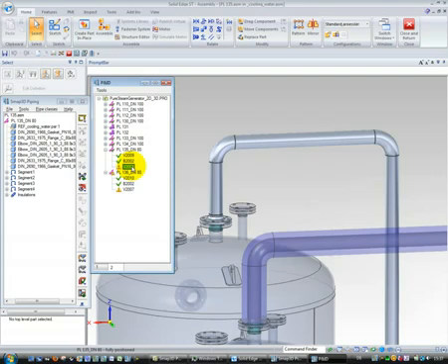And normally a valve is a kind of inner equipment, that means it belongs to a pipeline. So if it belongs to a pipeline and if this valve does also belong to the pipe spec which we worked with at the creation of the pipeline, then we can use these valves very easily from the pipe spec.